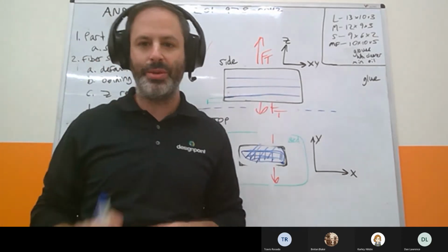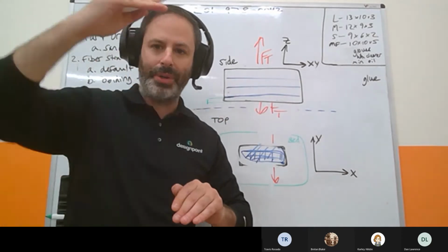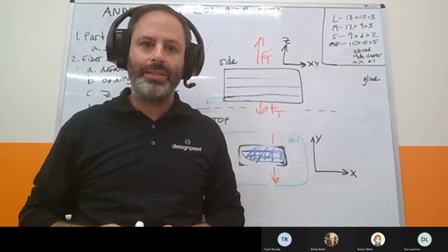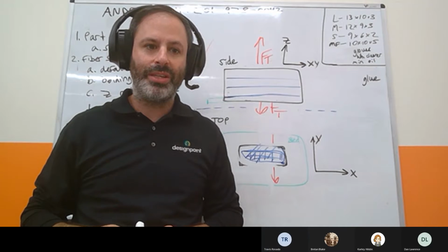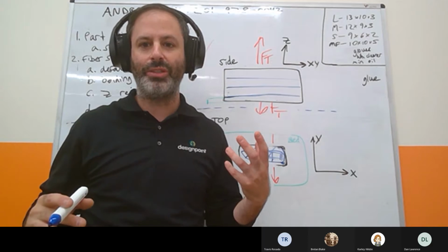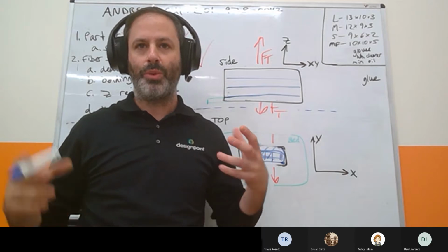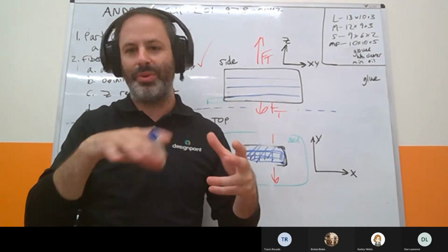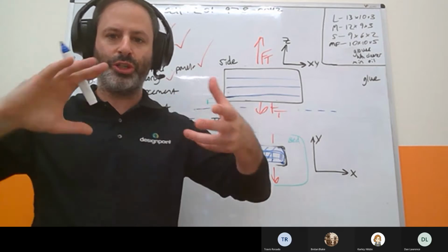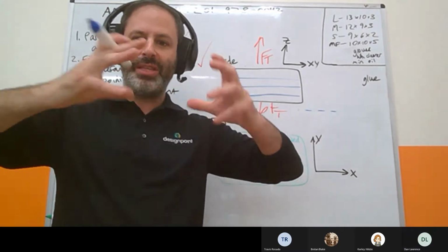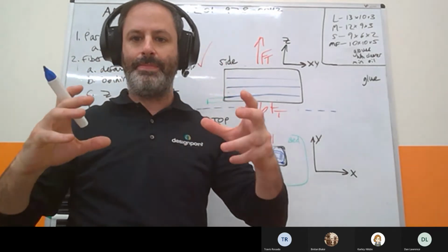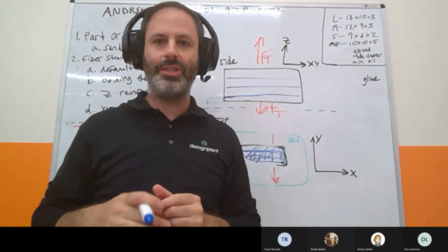But it's a real fast way. You basically just put it in and it goes boop, boop, boop, boop, boop, puts fiber on about every other layer. And certainly, it's going to give you reinforcement in the Z. It's going to give you reinforcement in the XY because it's a combination of perimeter fiber and potentially isotropic fiber if you fill it in with that instead. But I think it's also useful for torsional loads. If you had something that was torsional and it was along the full part, then that would be something to consider.